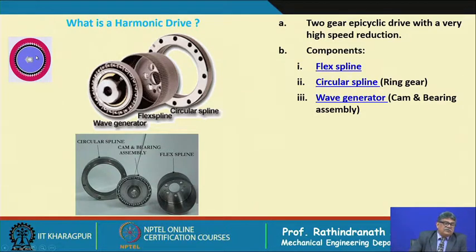As we look here, this is the oval shaped cam, but to give frictionless motion, or less friction, we have used a flexible thin bearing. Inside there is the cam, which is of this shape. This means that a solid cam is inside, of the same shape. You can consider the cam inside to be equidistant from the profile of this cam. It will be inside, and within this space there will be a bearing which is originally circular, but it can be made flexible. Now, I will show you these 3 components and how they are assembled.